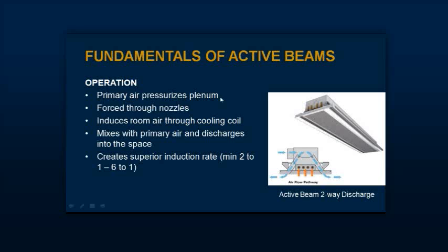potentially control it. Now, one of the real reasons that water systems have come to the forefront, besides being a more efficient media for transferring energy in and out of the building, is that the physical size of the elements to do this energy transport are much, much smaller than all air systems. For instance, the energy that I could take to cool or heat a building in an 18 by 18 duct could easily be handled by a half-inch pipe.